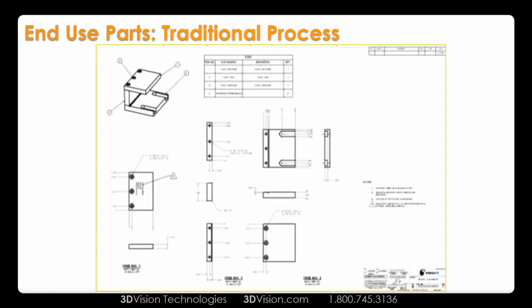Coming from a production engineering background, this is the part I despise. I hate taking the time of putting all this information into 3D and then putting it into 2D just so people in the shop could read it. Looking at this part, we have 3 different parts that are machined and then assembled. I've worked for a company where this wouldn't fly. Each part would need its own detail drawing, its own part number, and then an assembly drawing showing you how to put it together and calling out the nuts and bolts, having a bill of material.